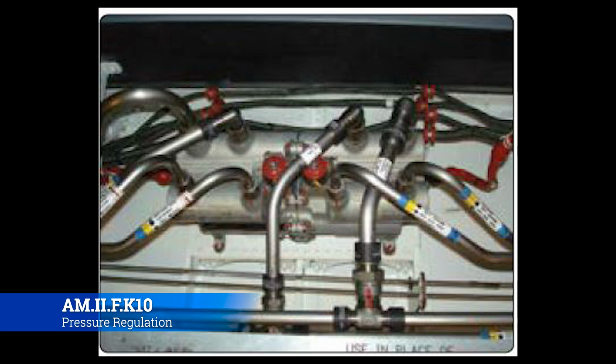So a flow control valve, and in this case, a servo actuator control valve, allows the flow of fluid to be changed, so that the hydraulic actuators work one way, and then with the same amount of power, can work backwards the other way. So in our scenario with landing gear, the actuators are going to push the landing gear down into the locked position, but then it's also going to have to grab it and pull it up whenever we pull the landing gear up. So the flow control valve serves a vital portion of this action.